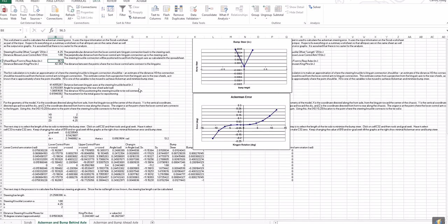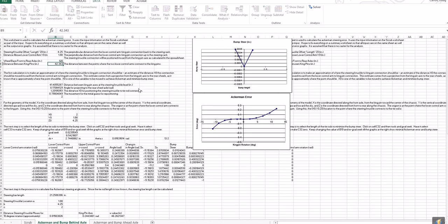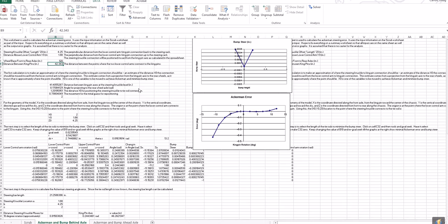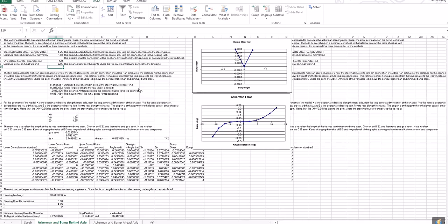The wheelbase that we're using is 120 inches, and the width between the two kingpin axes, we're using 52.5 for this particular example. So we put those all in there. The approximate calculations are done here, and please don't mess with any of those. This is our first estimate for x0, y0, and I've got it set up so that this is the goal seek here, and it's going to change this value t here to make the goal seek 0.